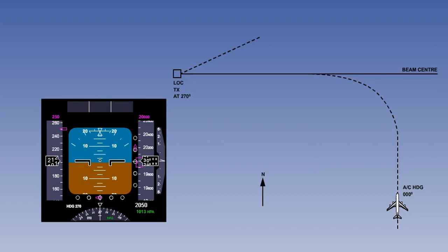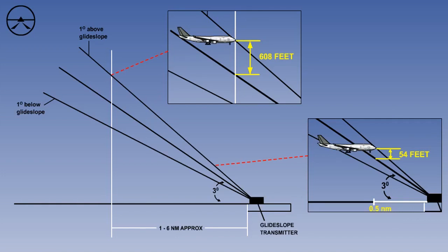The vital information to take away from today's lesson is that the flight director takes the raw information and provides either the pilots or the autopilot with computed information. This is derived from the rate of change of deviation and displayed as command bars on the primary flight display. During an approach, the flight director computed information must be modified as the approach progresses to reduce the commanded corrections.